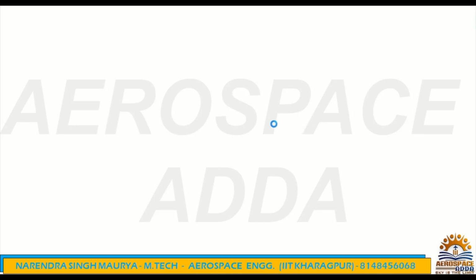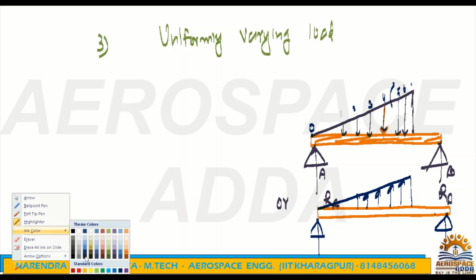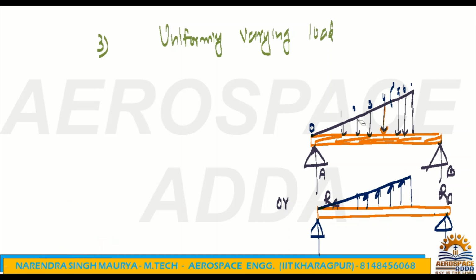If you check, even the arrow size is continuously increasing. So what is the meaning of it? That's the reason it is called uniformly varying load. It is continuously varying, it can be increasing or decreasing, but it is not constant throughout the length. If here it is 0, then further it can be 20 Newton per meter, that's possible, because here it is 0, it can be 10, 20, anything, but it is varying.